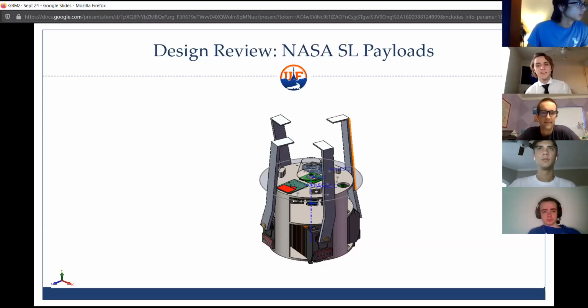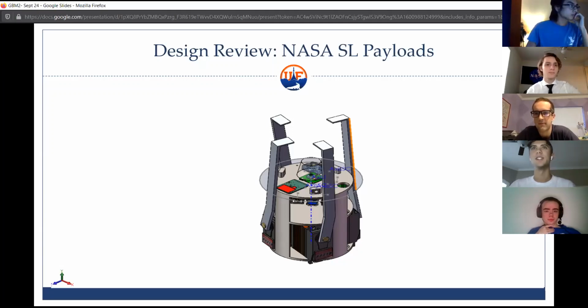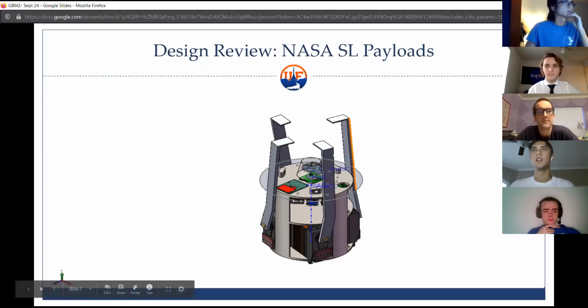You don't necessarily need a knife. You can have just a pin that is going through the fisheye that this is attached to, and then when we land, you could just rotate a servo. I know NASA last year had issues with just a single pin and a rotating servo. They did not appreciate that design last year. I did think of that, but they didn't appreciate it. They required it to be very over-engineered because they're concerned about the pin breaking or the servo breaking and releasing the parachute prematurely. So they normally want something a little bit more concrete.